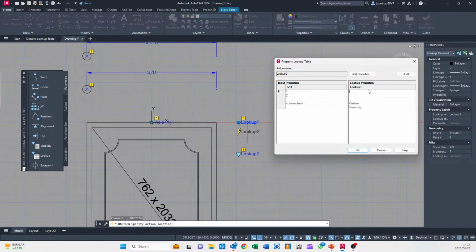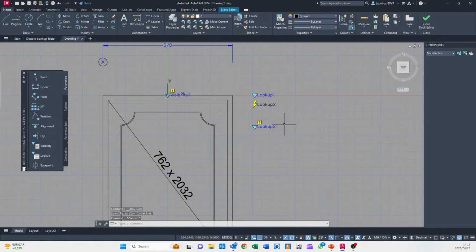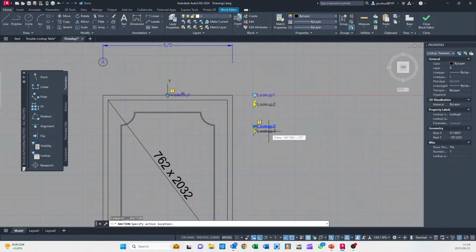And those two options on the lookup property side will be single, enter, double. And then what you must take note of is this read only must change. Okay, so when I press enter again, it changes to allow reverse lookup. So it's very important. Put your first entry, enter, add all of your entries, and with the last entry, just ensure that you press enter again and that it changes to allow reverse lookup. Okay, so press exit,